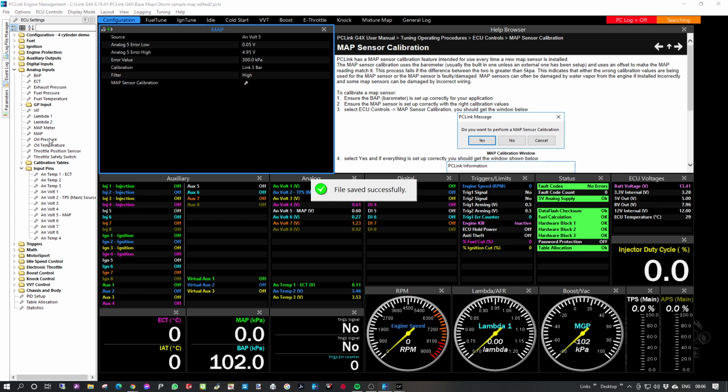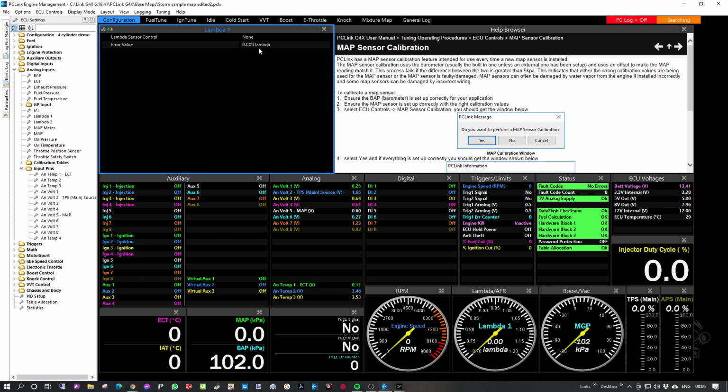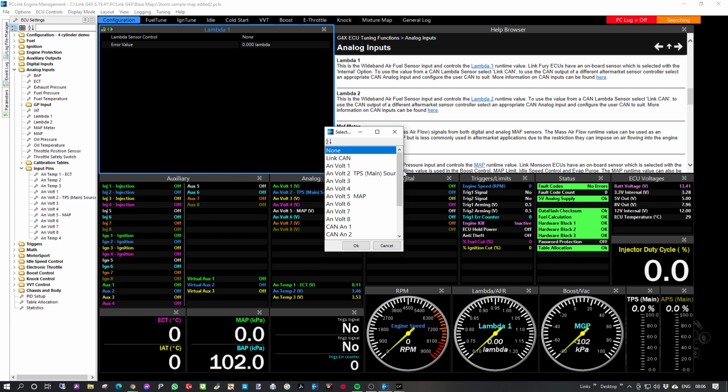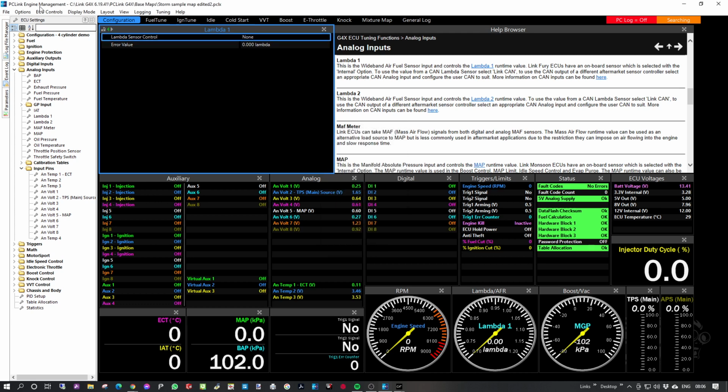Another pressure sensor is just oil pressure, but we're not going to get into all these sensors, as it's just going to be very mundane. One other thing is lambda sensors. With lambda you have a choice, because you can take it in over CAN now. And actually, there are CAN analogs for the other sensors. We'll do this in another video when we talk about CAN bus, and we'll talk about lambda in another video as well. But as you can see, we've started to calibrate the input pin setup here in a more meaningful way.